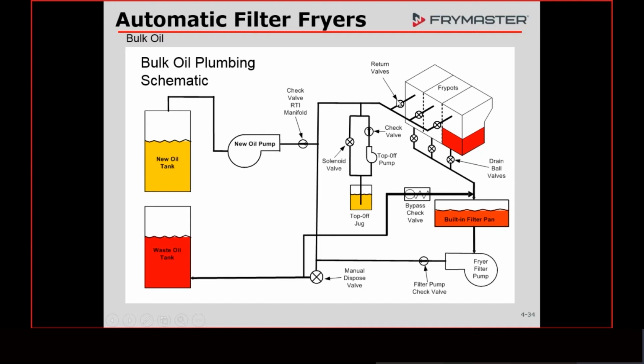If they didn't close all the way, even if you were filtering this one and this valve here wasn't closed all the way, you were going to get a little bit of oil in here. And then this one here, since it donated some of its oil over here, would be lower. So you would know when you would go in, okay, I just filtered and now we don't have any oil in here and this one here's got more, plus I seen those bubbles coming in, okay, here's where the problem is. We just got a valve that's opened up and it's not seated all the way. Most of the time it's not the valves. Most of the time it was the handle or the linkage.